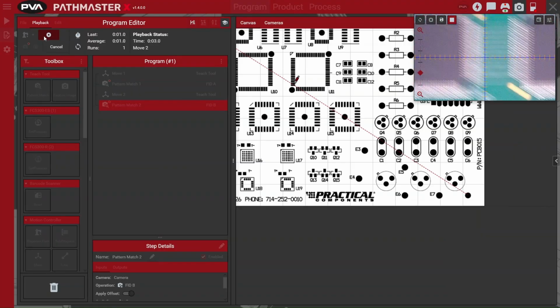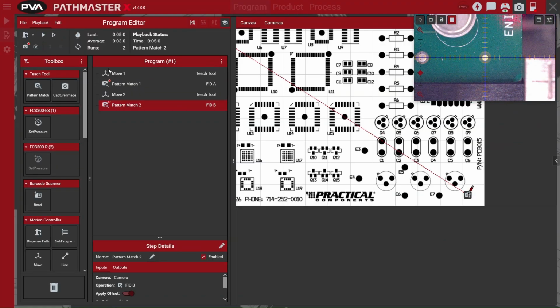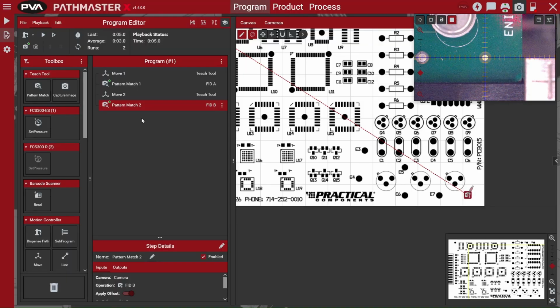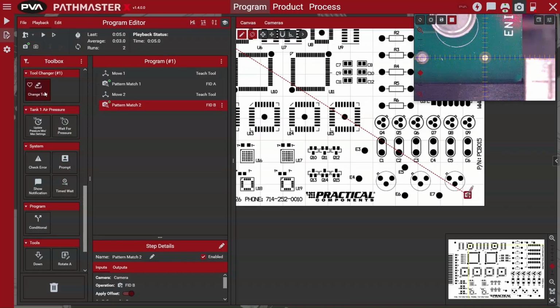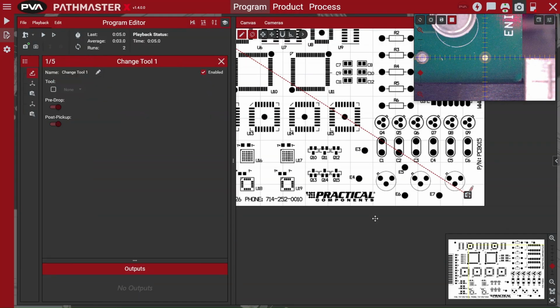When creating programs, some operations while using the tool changer require special consideration. For instance, some installed tools may impede a Z-mounted camera performing fiducial offsets, as the length of tools can cause crashes on purge cups, board stops, or other obstructions.